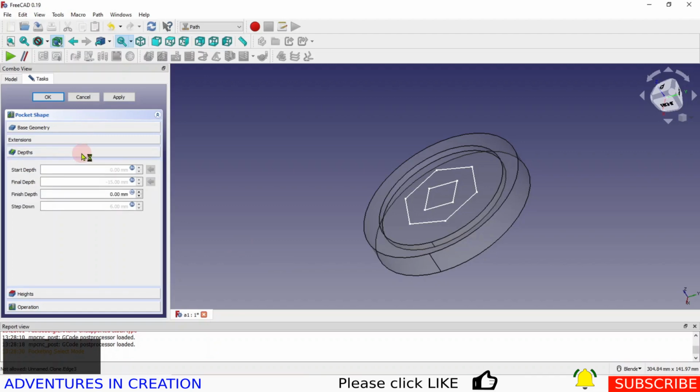Okay, so our depths. Now, we definitely don't want it to go into -15, so it should have really gone to that surface. If I click that surface and I click that arrow, you'll see that's -4. That's what we want it to be. And our finish depth, that's the final cut, basically. The final cut is going to be 1 mil.